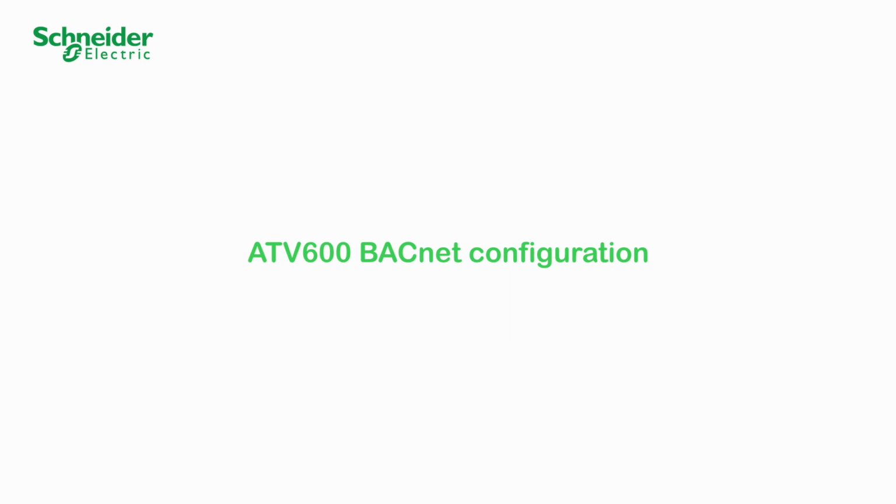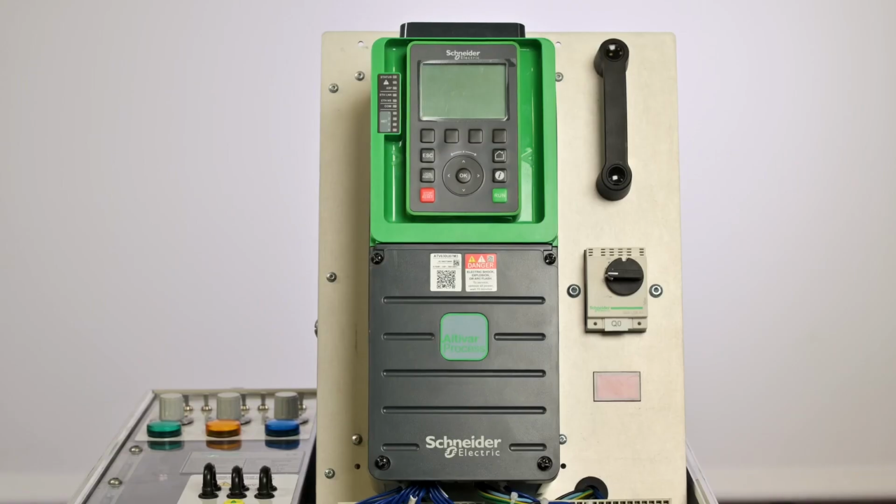ATV600 BACnet configuration. Install the BACnet Field Bus Module, BW3A3725. The BACnet MS/TP Field Bus Module is only supported by the ATV600 from software version v1.7 and later.